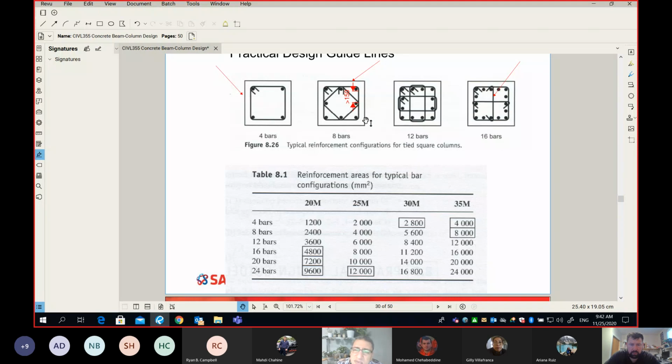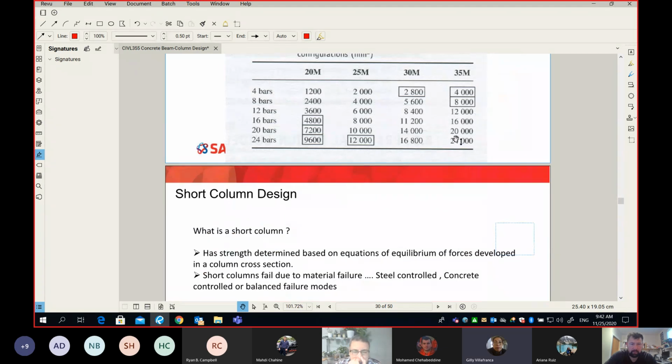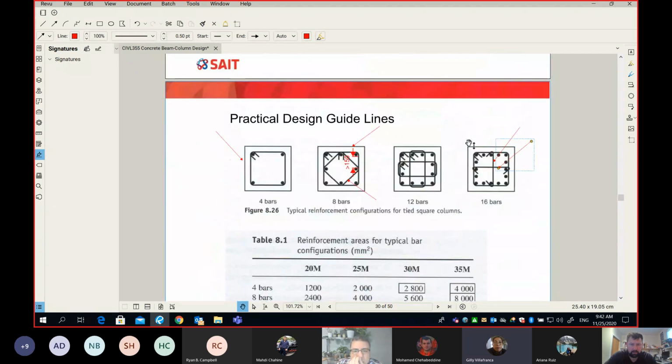Really, what's better for me, I go with this one. So this one is my way to go. You can tie it very well to your cage, but this one is very weak. Mostly those will fall down during construction. Well, it also depends on the angle of your hook. If you make it a little bit tighter, then it will not fall. But I doubt it; those are very weak. I've seen them on site. They are always a problem. Okay.